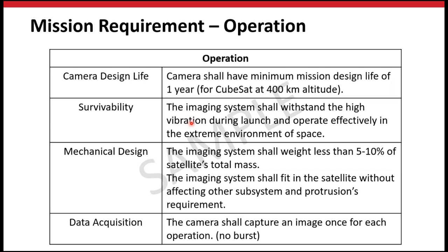In terms of operational requirement, this is related to the CubeSat as well. What CubeSat do you choose? Is it 1U, 2U, 6U? You need to make sure that the operation relates to that CubeSat. So you need to look into the camera design life, how long the camera that you designed can last, the survivability, whether it can survive the extreme environment of space, and also survive the high vibration during the launching, the mechanical design.